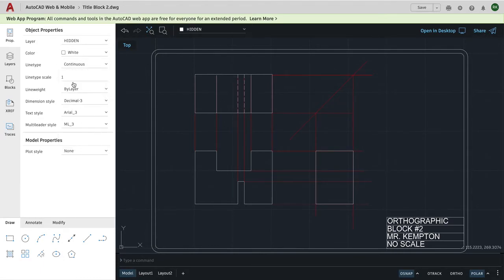Take this back to dash. Size 10. And again, you have to be pretty deliberate and patient with this software. Being online, it's a little bit slow. And I'm going to draw now 2 lines across here representing this feature that we cannot see from the right side view. Looking at this object from the right, we can't see these 2 cuts, but we know they're still there, so they are represented by dotted lines.